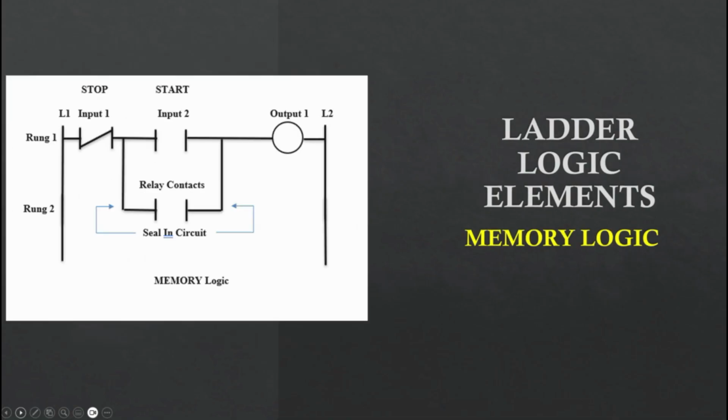And finally, the seal-in circuit. This is essentially one of the key wiring scenarios in the lab that you'll do. Wiring a seal-in circuit, commonly used for what are called start and stop stations, provides wiring that you have coming from the load side of the stop button through the auxiliary set of contacts or the secondary contacts used to seal in or close this circuit and hold it, and then comes out of that set of contacts to the load side of the start.